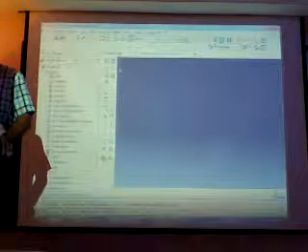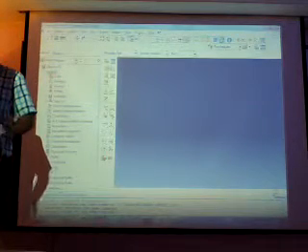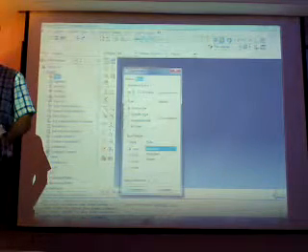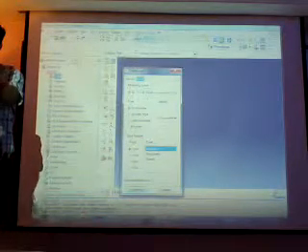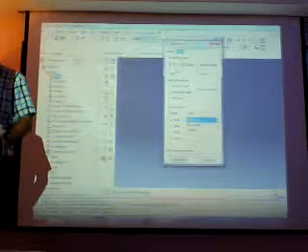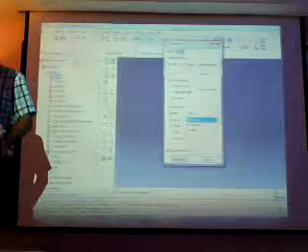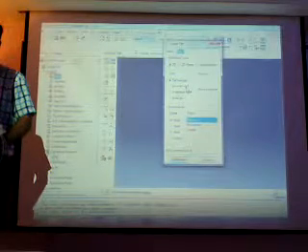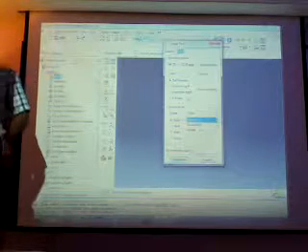For creating a part and doing your simulation, first, we need to define a part. We double click on the part in the tree, and you can take your part as 3D, planar, or axisymmetric, and different types: deformable, discrete rigid, analytical rigid, or Eulerian.